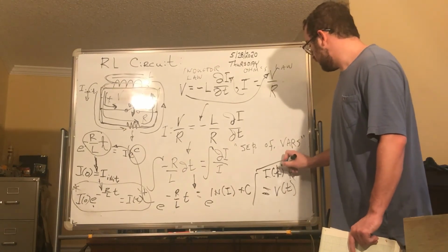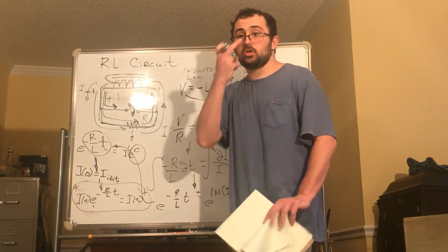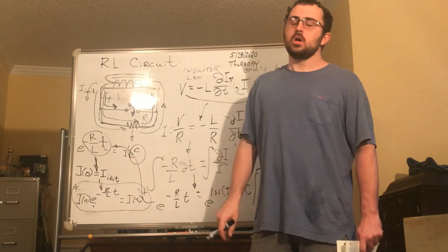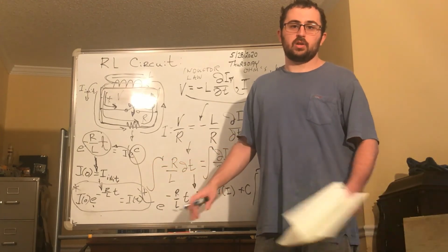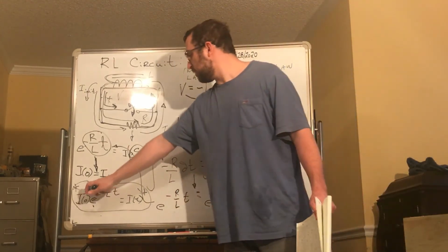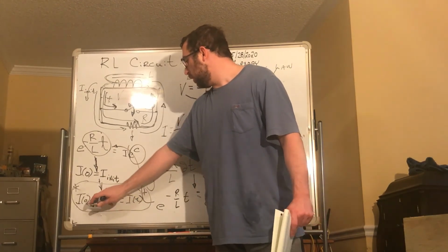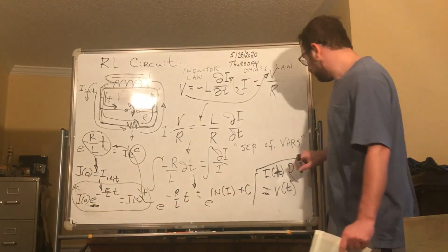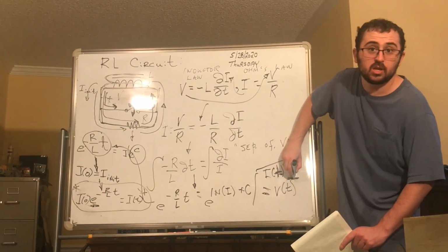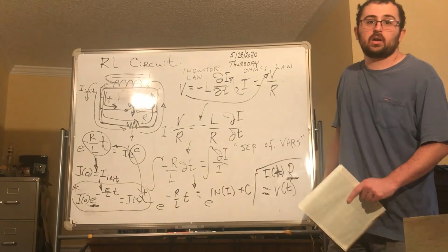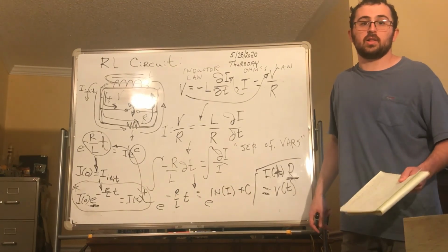Now the problem is this function is very intuitive. Larger resistance cuts the current faster, larger inductance slows down the current's decrease. Very intuitive. A larger initial current scales the exponential here, where e is the natural number. If we make R too large, the inductor puts a very large voltage across itself, which is very problematic because it can shock you and it can break transistors and other things.